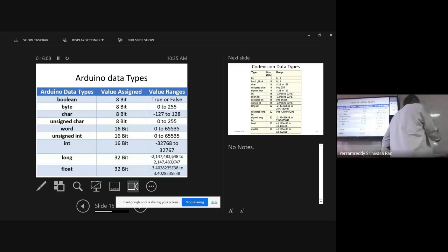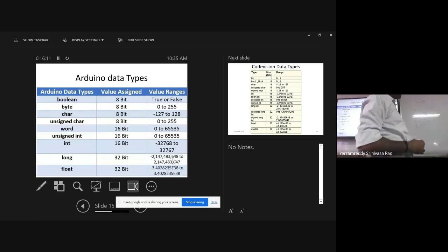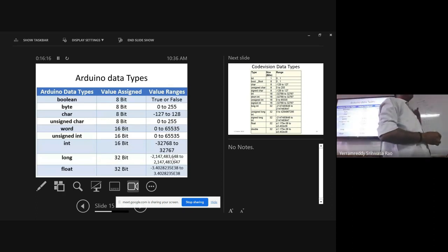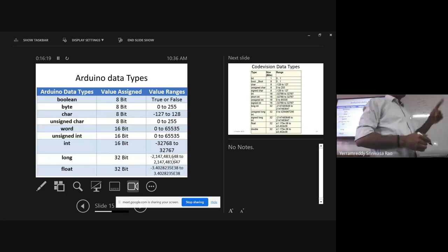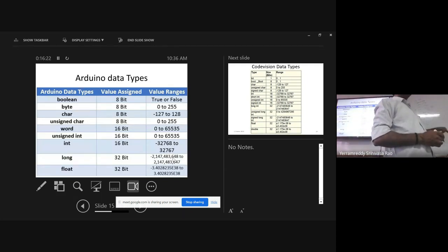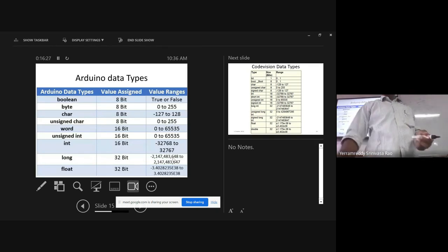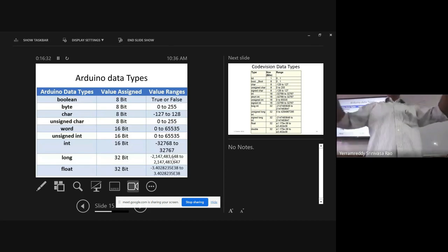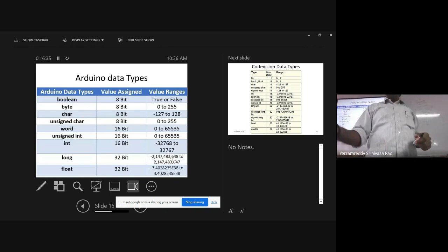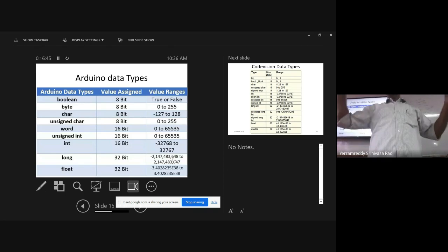D0 to D7. Means what? Here, for example, 8-bit data is there. How many wires are required to connect between transmitter and receiver? 8 wires are there. In serial communication, how many wires are required to connect between transmitter and receiver? Only one wire. That's why your USB is so thin. Though you are sending, God knows, 32-bit data, 64-bit, whatever you are sending, there is only one wire. One is VCC, other is ground, and data line, D plus D minus, differential data. Only one line. Through one wire, you are sending whatever the data you want.